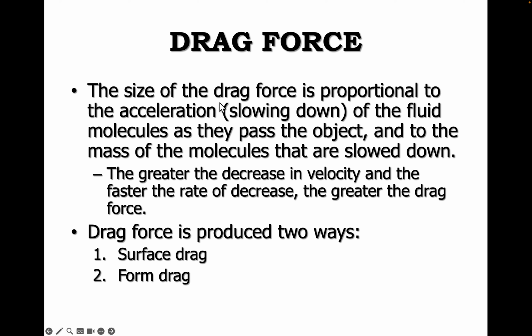So with our drag force, the size of the drag force is proportional to the acceleration, in this particular case the slowing down acceleration of the fluid molecules as they pass the object, and to the mass of the objects that are slowed down. Meaning that the greater the decrease in velocity and the faster the rate of decrease, the greater the drag force. So again, as I've been talking about before, more velocity means there's going to be a greater amount of drag force on that object in a fluid. And drag force is produced in two different ways. We've got surface drag and form drag.